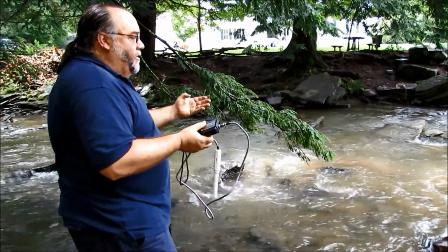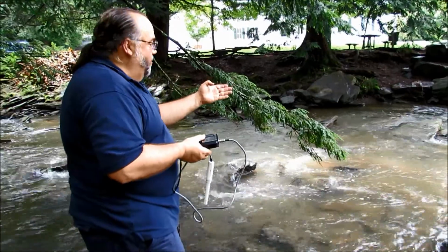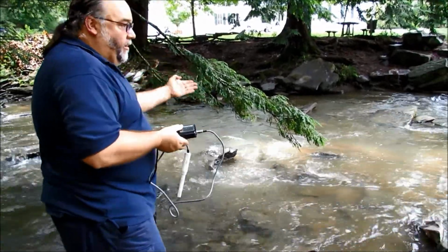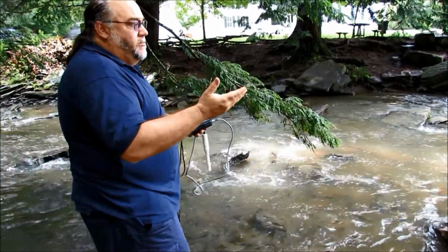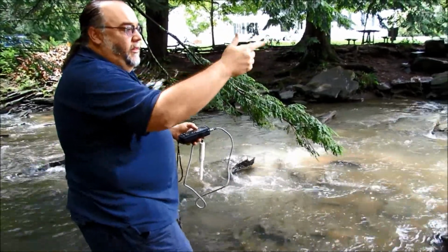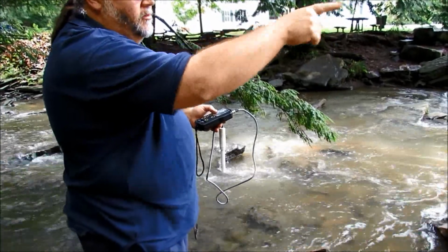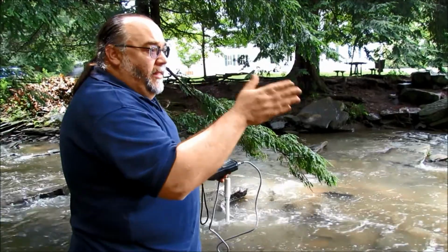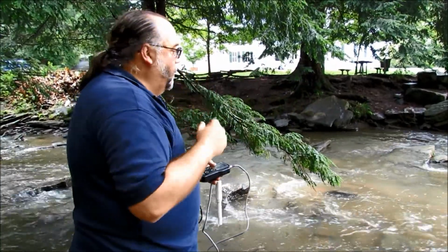One of the things you always want to do when you come out to a site is photo documentation, and you're going to kind of gauge the clarity, what's going on. So you have that staff gauge you want to put up. Probably the best thing is to put it in a place that's always wet. So maybe you can go to Ben Meadows and pick up an actual staff gauge and mount it to that wall over there. Okay. And so when you want to see how high the water is, it's always mounted at that one point for you, so you don't have to keep wading in.